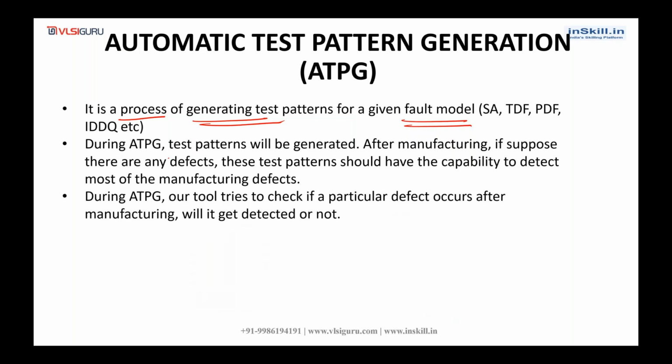There will be various fault models which we will be discussing, like the stuck-at fault model, transition delay fault model, path delay fault model, IDDQ fault model. Like that, there are various fault models which we'll be discussing.